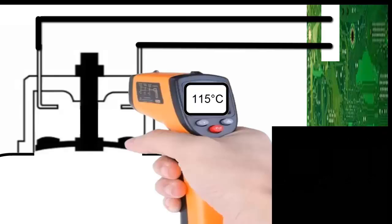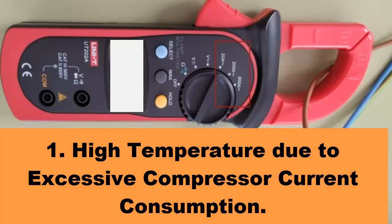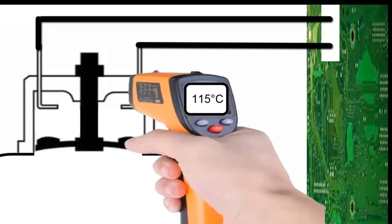Possible causes of the H3 error code. 1. High current in the compressor. This can be caused by a short circuit in the compressor, a defect in the wiring, a problem with the electronic board, or low power supply voltage from the external electrical network.